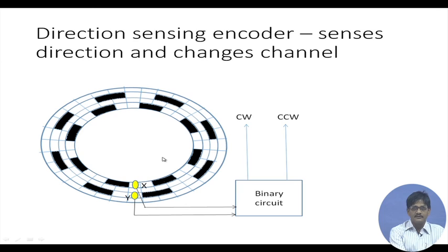Just a moment. Yeah, in that case, y pulses will precede... I should have said, in the clockwise direction the y pulses will lead the x pulses, and in the counterclockwise direction x pulses will lead the y pulses. Now, what do we get out of it?